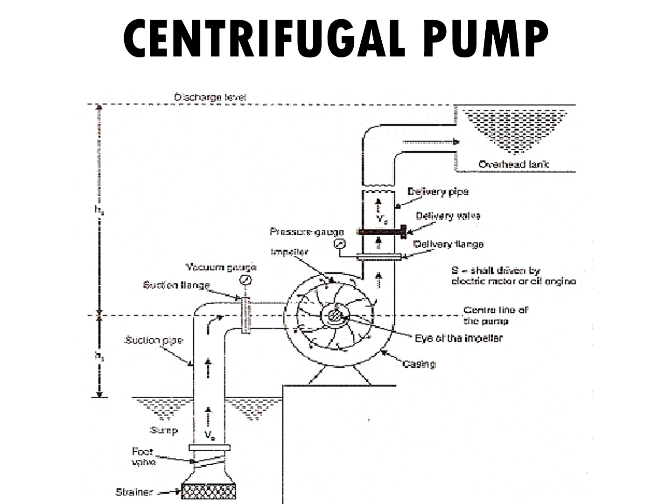So this is a figure showing the construction of a centrifugal pump along with its working. From the impeller point of view, you can divide it into two parts. That is, below the impeller you have the suction side, and above the impeller you have the discharge side or the delivery side. Accordingly you can denote it as HS, which you can see in that figure. HS means suction head and HD means delivery head or the discharge head.